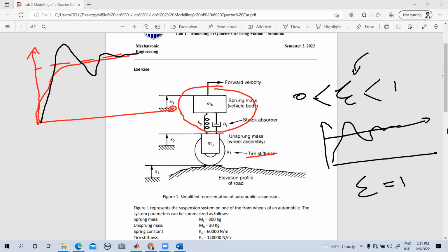In this sort of case, the poles are on the real axis, but there are 2. You want to try to make these poles coincident, right? So that you have only one equal pole. That's when you get this. You call this a critically damped system, right?